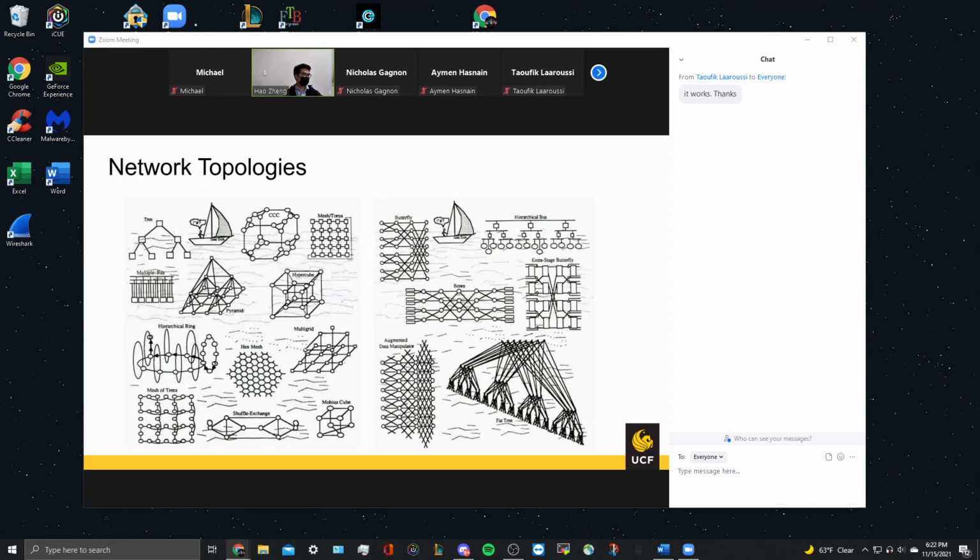Another team is to design the memory system: how many caches, what's the size for the register, the cache and the memory system, what's the addressing mode, set associative, fully associative, direct map. And then the third team, once the previous two teams confirm their design, is to select an appropriate interconnection network to connect these components. If you were given this task, how do you select and design the topology?